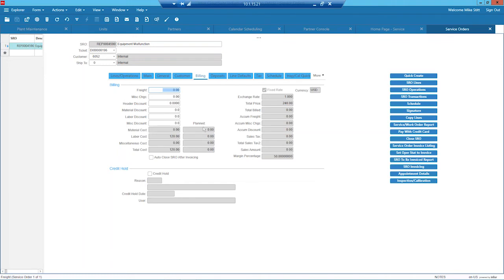like on this particular repair maintenance work order, what kind of costs did we accumulate? How much material cost, how much labor cost, any kind of miscellaneous costs. So you get a nice idea of cost. So through time, you can get a good sense of the cost to maintain equipment in your plant. So these are the typical things that you would address on a maintenance work order.